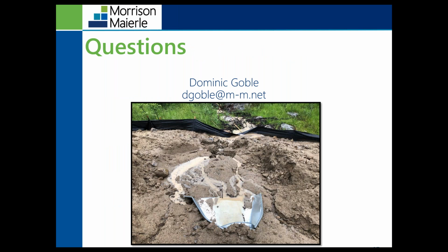So I want to conclude this webinar with the photo that was at the beginning. You can see right here again that this BMP is a culvert with outlet, but there is no riprap, no outlet protection. So it's resulting in erosion, which is resulting in sediment being carried through stormwater, which is then overtopping that silt fence and being discharged into surface water. So make sure you're not just relying on sediment control as protection, but you're having erosion control BMPs at the source, controlling that stormwater, minimizing velocity, and keeping the dirt in place.